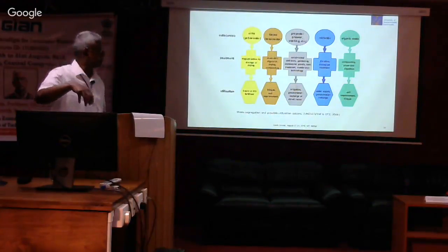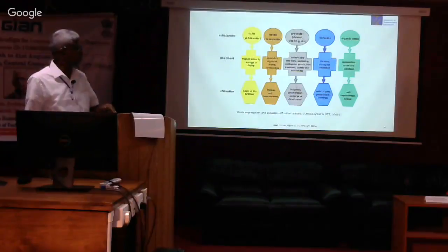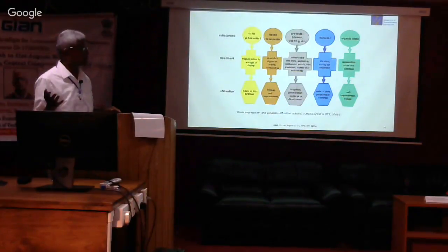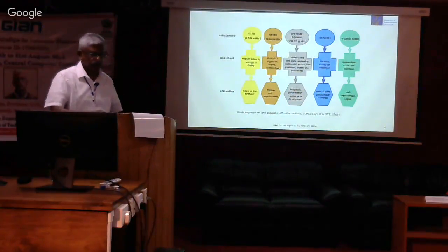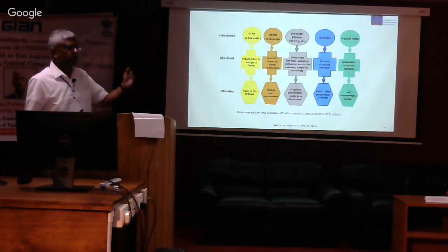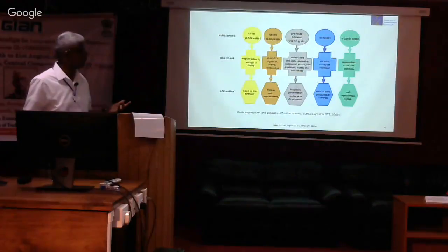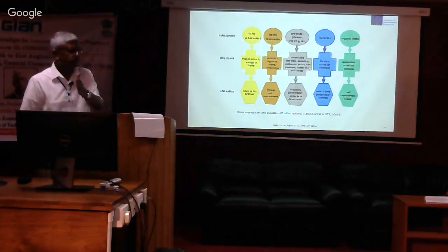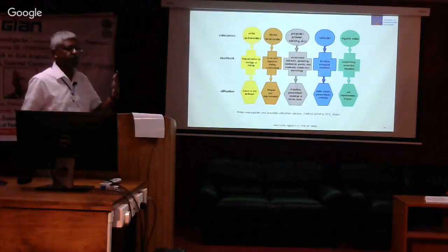So what many parts of the world are doing is they treat this water, convert it into drinking water, but they don't use it as drinking water. They just use it to recharge the ground. Because as you know, groundwater depletion is also a major issue. We pump so much out of groundwater that we are pumping at a much faster rate than the natural replenishment rate. So if I put this into the groundwater, then it is recharging the groundwater. And then later on, when people withdraw groundwater, the public perception is that this water has flown through some filter in the ground, and that has taken care of any remaining contaminants which were not treated.